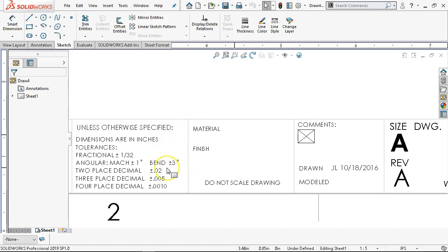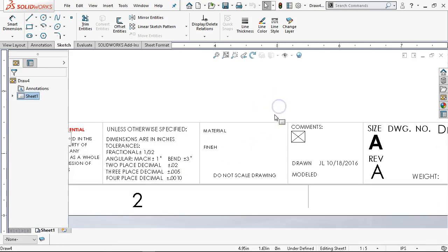Sheet metal bends, those are really at the mercy of the machine and the operator doing the bending. And so plus or minus 3 degrees is pretty generous to be able to get into sheet metal. So one of my favorite oxymorons is precision sheet metal, which is harder to say than I thought.